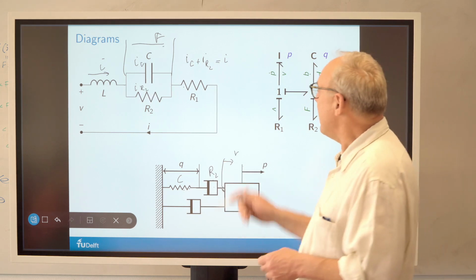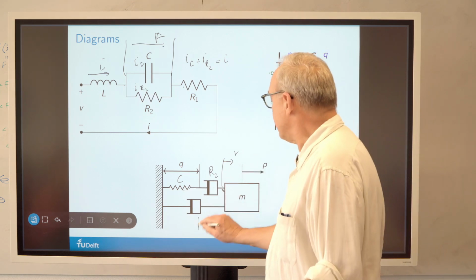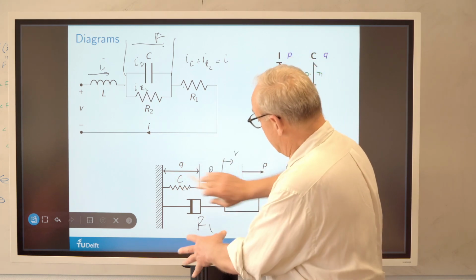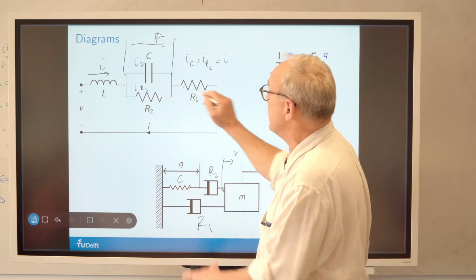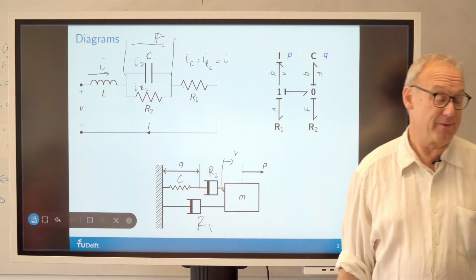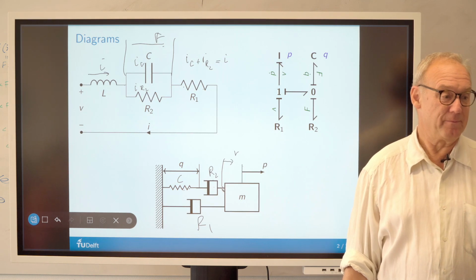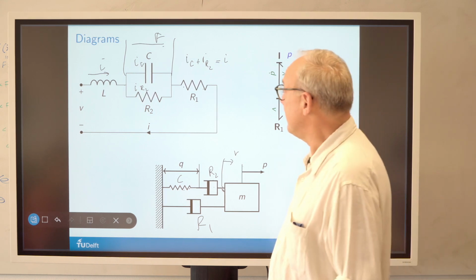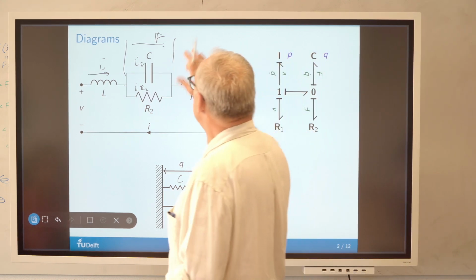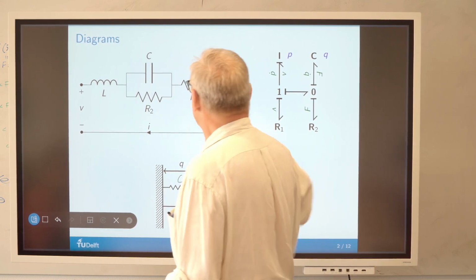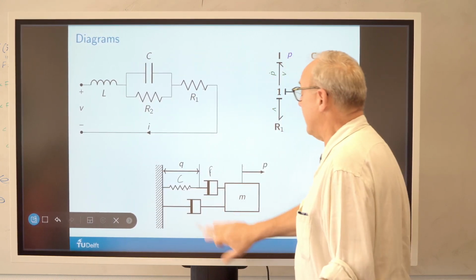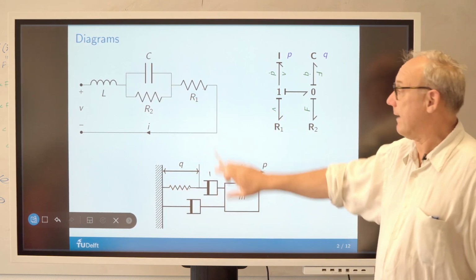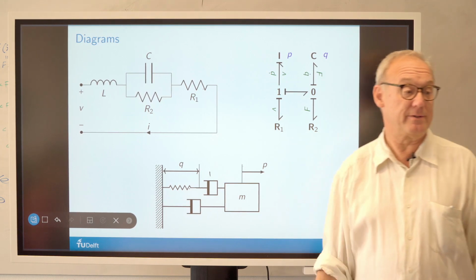So, inversely, this damper here is in parallel with this damper spring system, but here it's in series with the damper spring system. Correct? All right? So you see that to get this thing right, you have to take everything that's here in series and make it in parallel, and everything that's in parallel here, you've got to put it in series. All right?